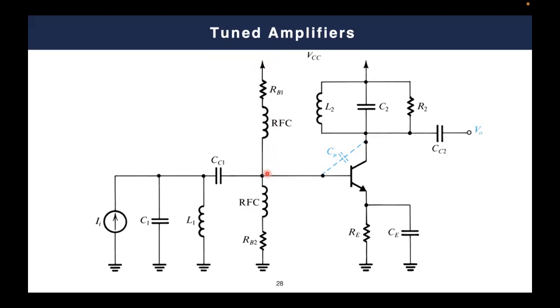But for this circuit, on the other hand, you don't need to have this resistance in the AC analysis. So you need to get rid of this resistance in the AC analysis. You just need this resistance as a part of the DC biasing, but during the AC operation, you don't need such a resistance. So what you typically use is what we call an RFC, or radio frequency choke. What is a radio frequency choke? It's a very basic use of inductors in the tuned amplifier.